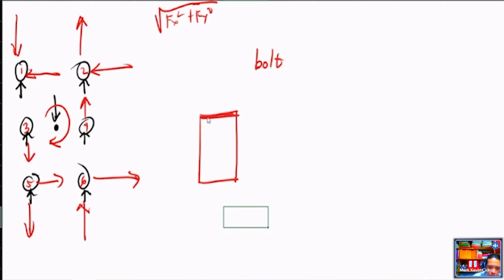If you have a fiber here and a fiber here, and those fibers are at the same distance from the centroid or from the neutral axis, their magnitude is the same. Only the direction is different: this one is in compression, this one is in tension. It is also the same with torque. And the shear stress from the torque is equal to TR over J.